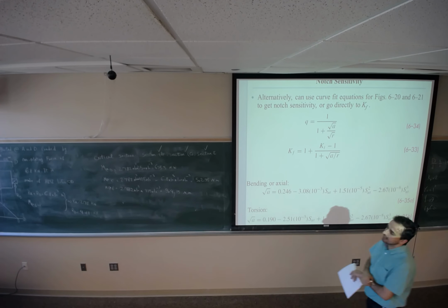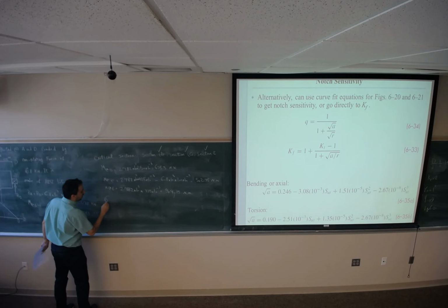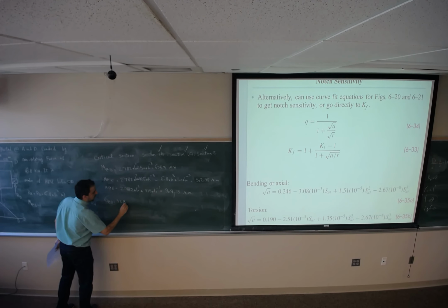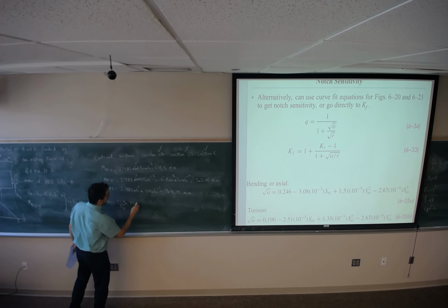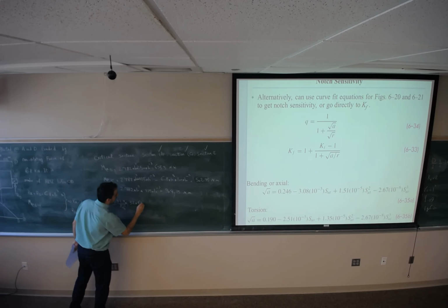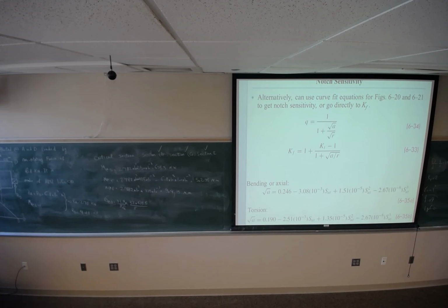Next step is finding the stress at points B, C, and E. I have the bending moment applied to point B, and sigma at B would be 32 M over pi d cubed for section B. 32 MB is 695.5, pi, diameter is, this is 32 millimeter, this is 35 millimeter, and this is 38.